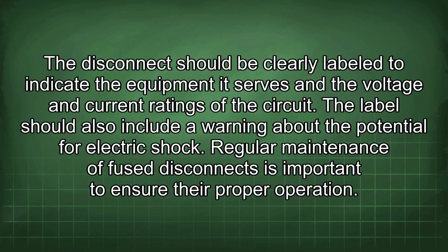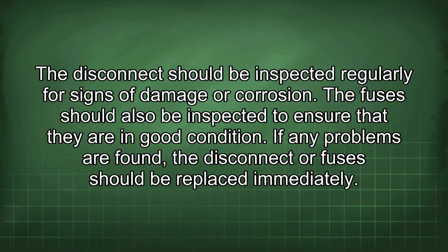Regular maintenance of fuse disconnects is important to ensure their proper operation. The disconnect should be inspected regularly for signs of damage or corrosion. Fuses should also be inspected to ensure that they are in good condition. If any problems are found, the disconnect or fuses should be replaced immediately.